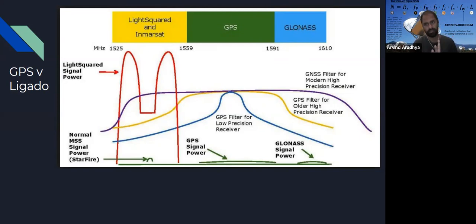If I'm licensed to transmit at 100 megahertz and I kick up my transmitter to full power and amplify my signal, I get some signal at 100 megahertz and some at 200 and 300, and the power level drops. It's much lower than what I'm supposed to be transmitting at 100, but there's still something called out-of-band emissions, and that's the problem here.